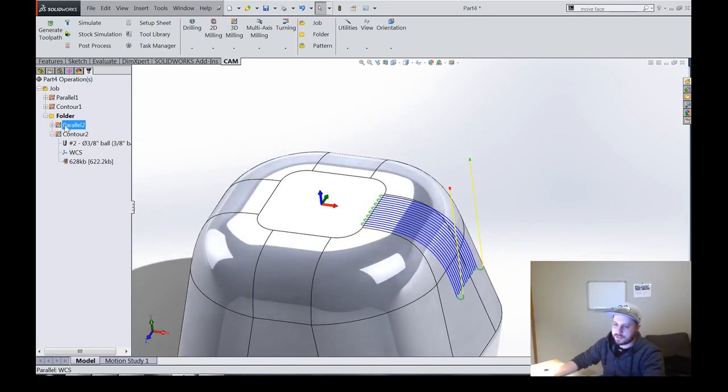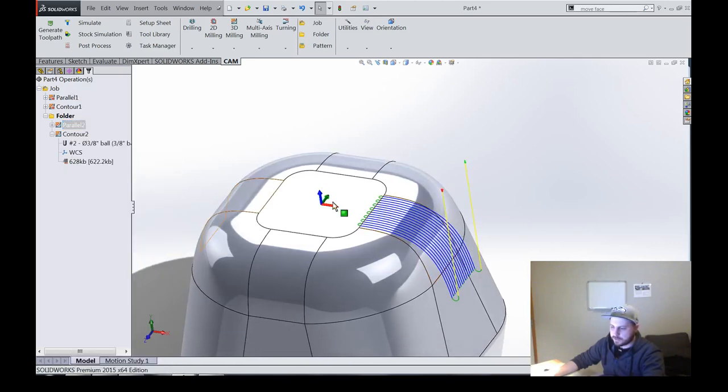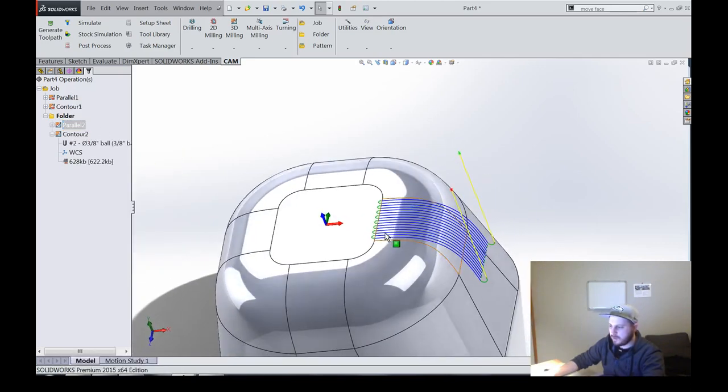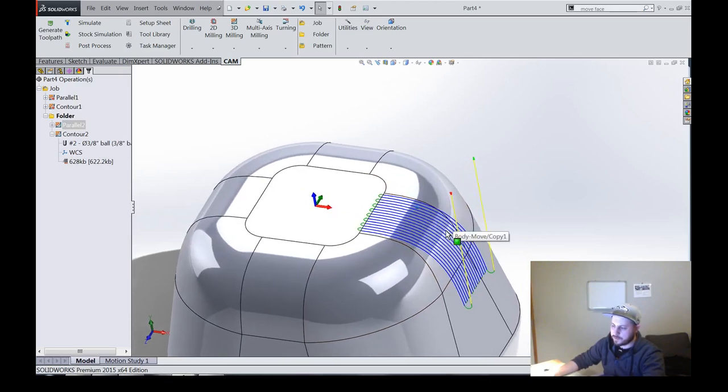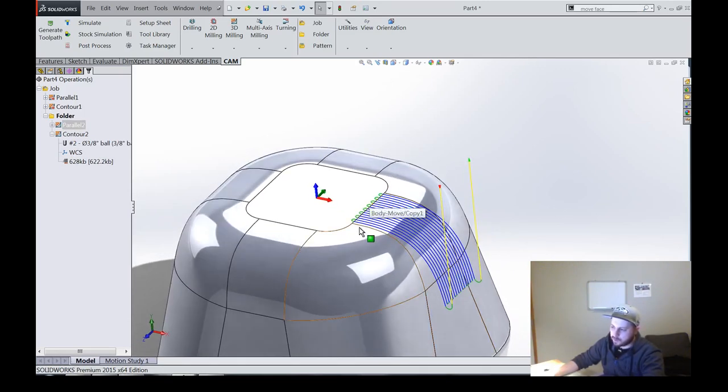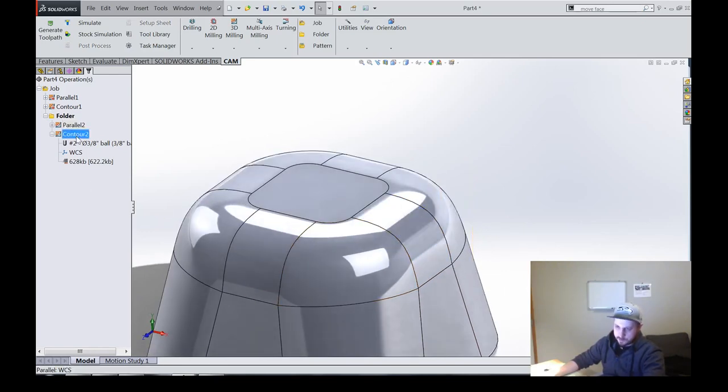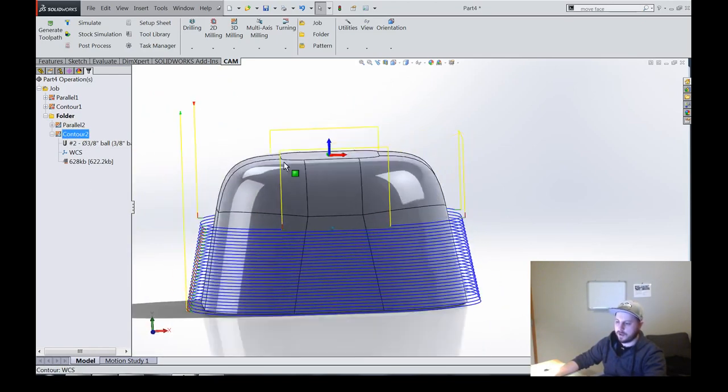Fairly basic stuff like that. Parallel, I mean, you can see this is pretty good. You maybe would want the toolpath actually to run the other direction to accentuate the curvature in the other direction, or to at least have more constant surface speed. All that kind of stuff. But this is pretty good. That's pretty serviceable.